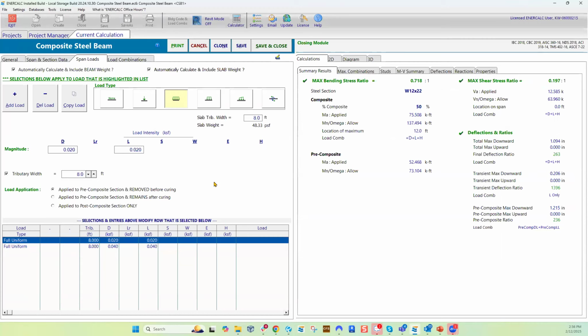Yes, that's correct. Whenever you are designing a composite member and you are designing it as unshored, that means the member is not shored. Once you start putting the loads, you need to be able to distinguish what loads are applying to the member before the extra capacity is achieved. You get extra capacity from a composite action. However, you don't get it from day one.